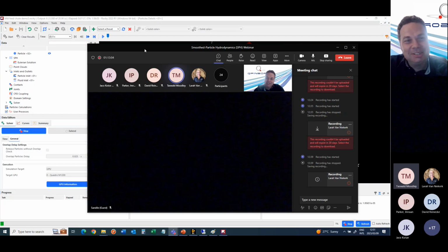What I noticed is when I'm restarting a simulation, what I'd normally do is fill up my DEM particles. So how I thought I'm going to do the simulation is I'll fill up my DEM particles, and then I'd load my SPH particles thereafter. So I created inlets and did that in that order. The problem is, let's say now I want to change the SPH mass for another simulation.